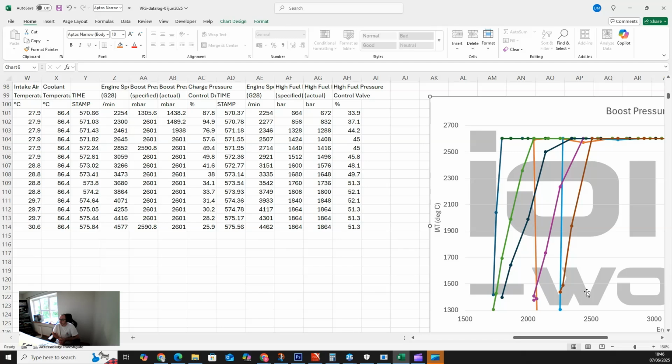I say this a lot: not all data is useful, so you want good, useful data. You don't want to just be plugging in a diagnostics, going down the road reading stuff, and half-assed going, oh, that looks a bit funny. You want to nearly structure a test plan. What do I want to get out of the data first, and then work back from that and say, okay, how am I going to test to give me accurate data to prove out this point? Can I see is my fuel system working okay? Is my charge pressure control working okay? And so on and so forth.